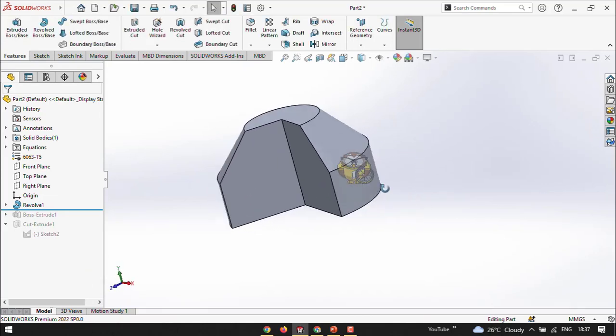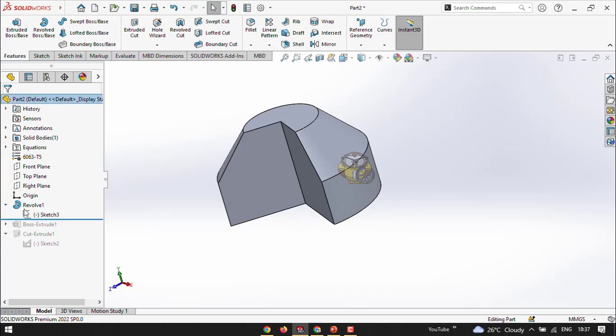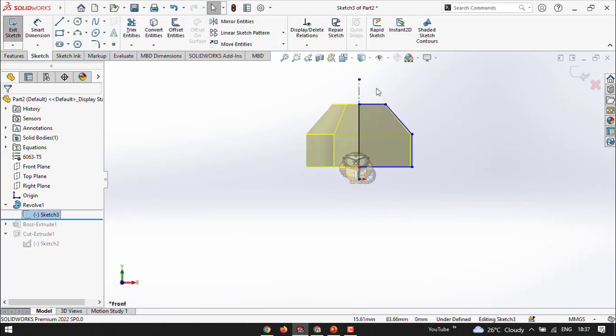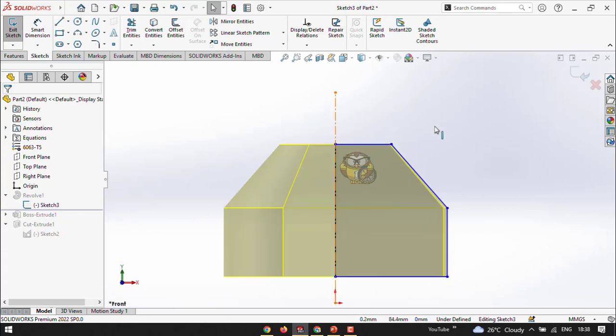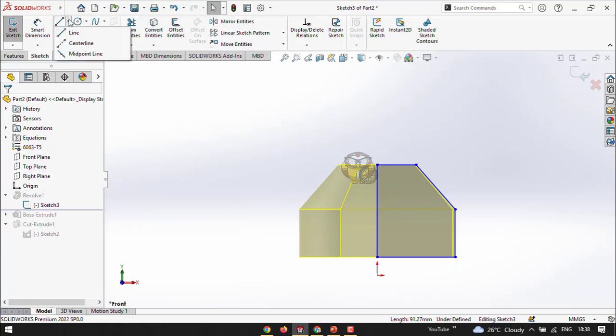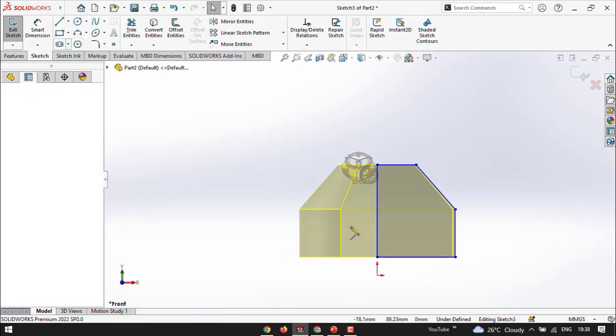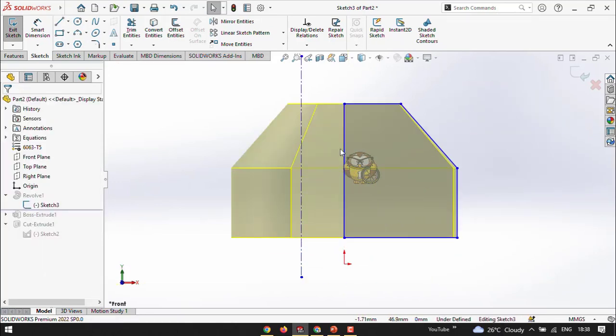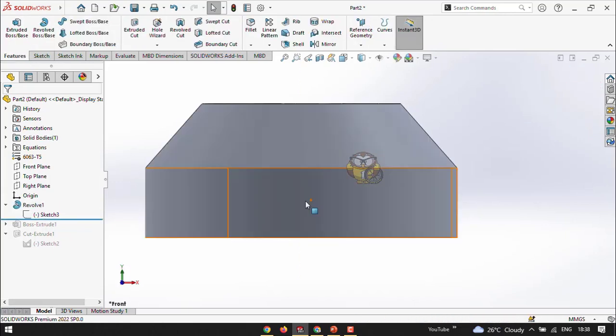Okay, I have another doubt. So I'm going to change my center line. I'm going to edit. Now in my screen, I'm going to select the center line and delete it, and change my center line to some other place, like this here. So you can see now the blue color, this is my sketch. Initially I created the center line on the origin point. Now I move it a little bit outside. Now I am going to update.